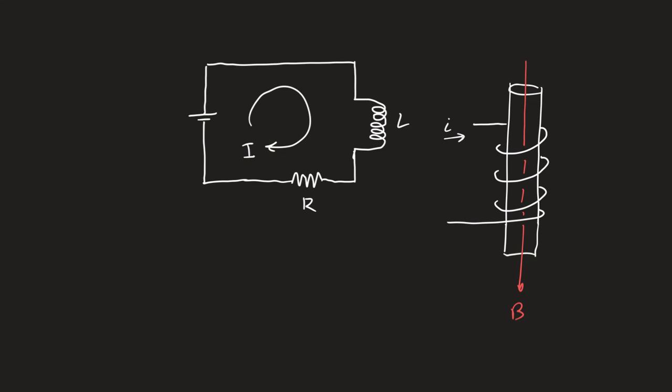Now, we good? When the circuit has reached a steady state condition, there is no back EMF. An inductor is invisible under these circumstances because it's just passing current. An inductor is only at play when the current is changing.